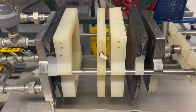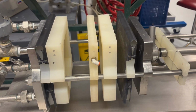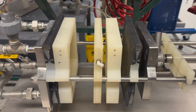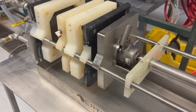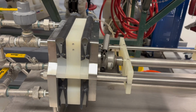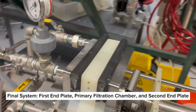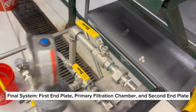In industry, and for large amounts of slurry, the mixing plate and secondary filtration chamber may be necessary. However, for a small-scale laboratory setting, both are excluded, and the final system only consists of the two end plates fitted with filter media and the primary filtration chamber placed in between them.